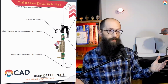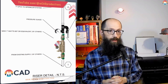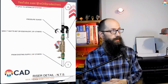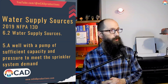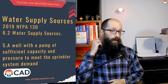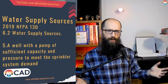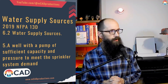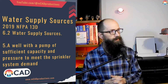This is just a valve in the wall to keep the water from the sprinkler system from mixing with the domestic, and then we have a drain on the side. So let's see, okay, besides connection to a city main, another common thing we have for houses would be a well, or also we have cisterns a lot here in Central Oregon, which is basically a well with a concrete tank.